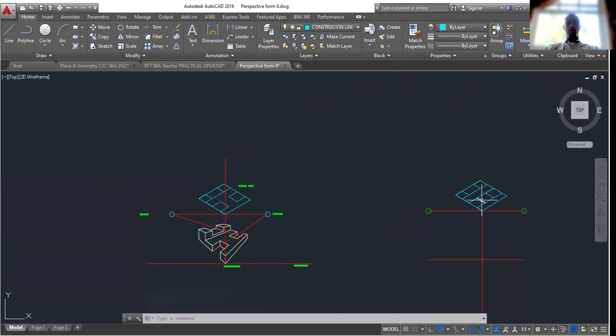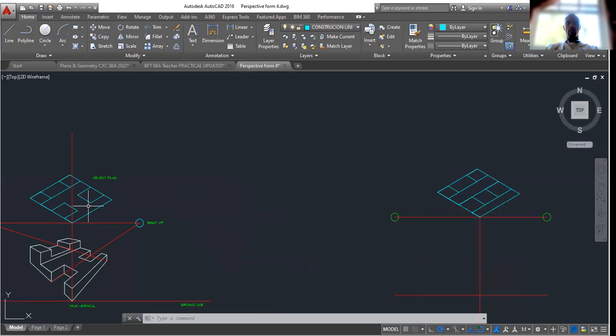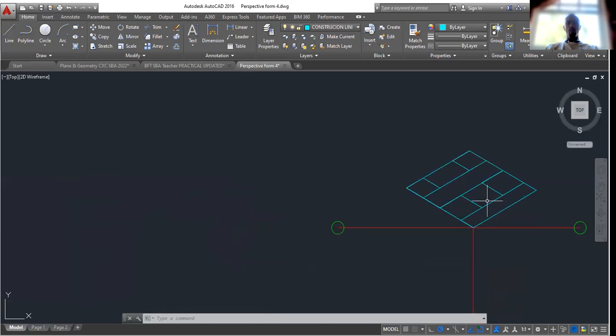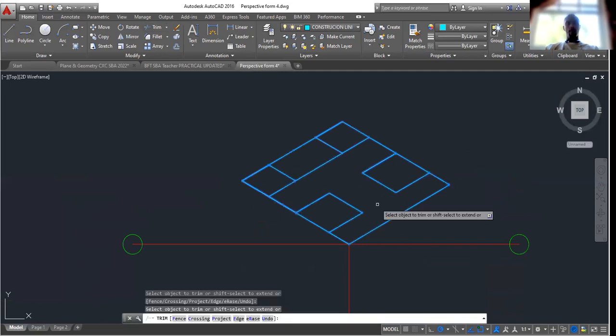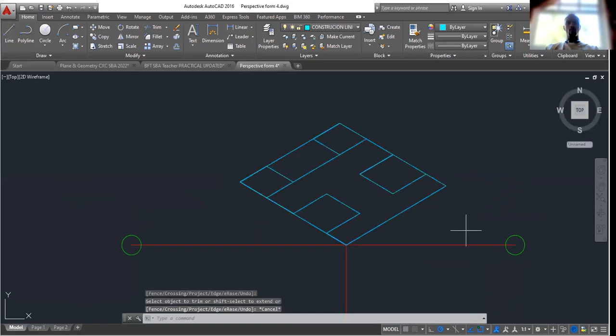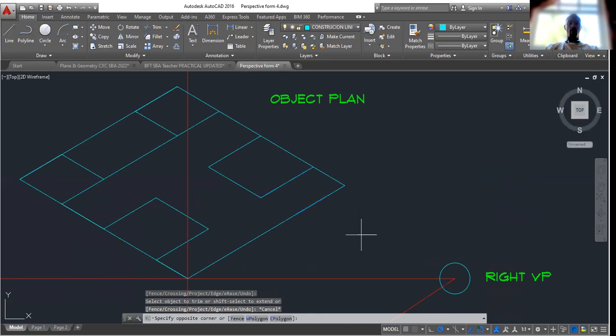Well, we can trim out these gaps here on this side by just selecting our entire drawing, click on trim, then we select what we want to get rid of, and that is it. Now we can also get rid of this part because it's not included. We can get rid of these as well, although I included it in the other drawing, but that was my mistake. So I'm also going to trim out these two portions there. Okay, so that is it for the setup.